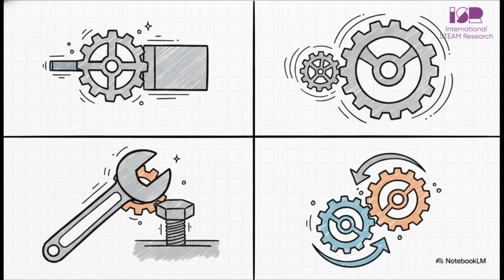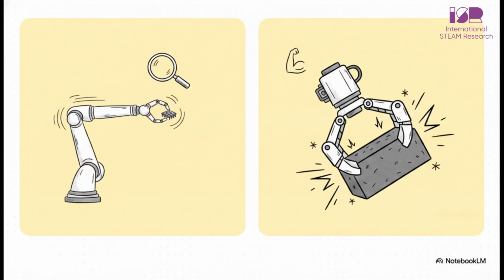Let's move on and see how this builds into Section 3, the ultimate gear toolbox, exploring the 9 types of gears. First up, we've got the most popular group, spur gears. These are cylindrical and they have straight teeth that run parallel to the shaft. They're super simple to produce, and they don't create any axial thrust burden, meaning they don't push sideways against the machinery.